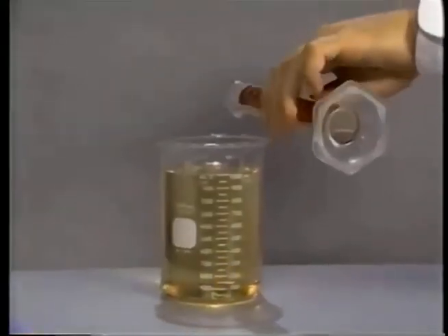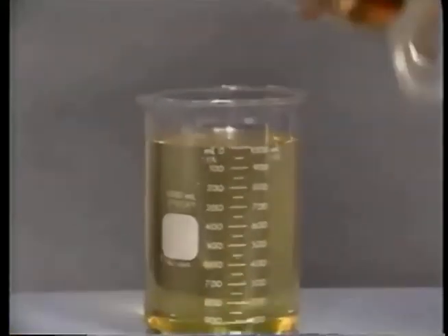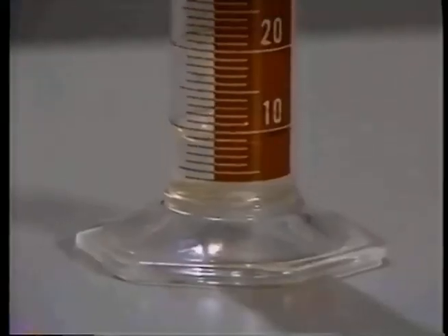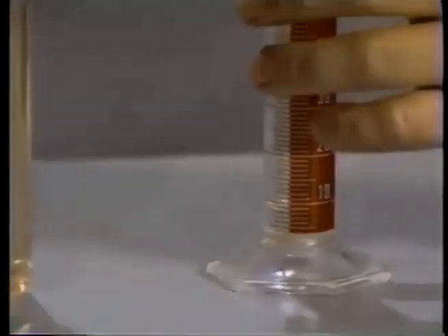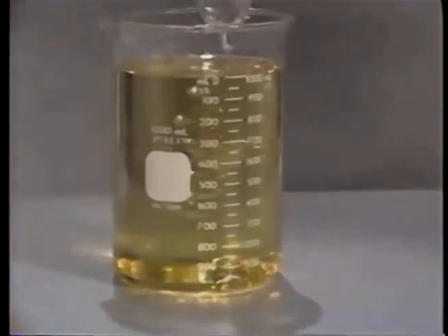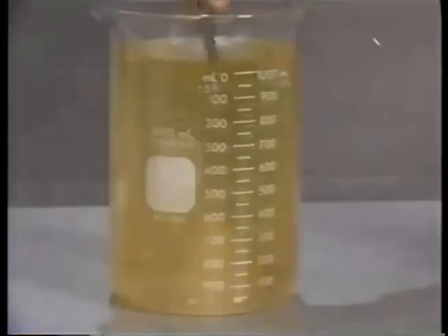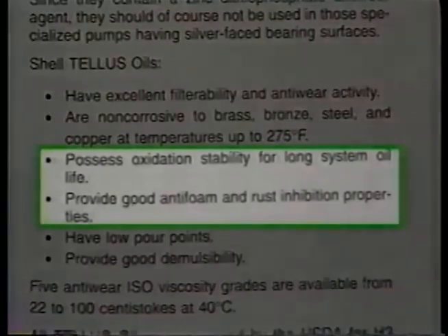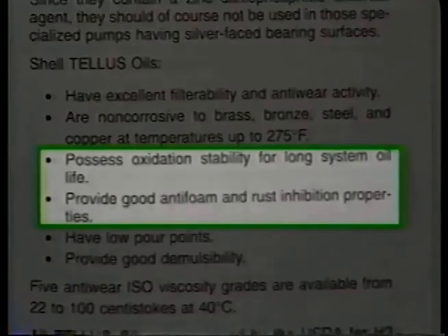Even small amounts of water in petroleum-based hydraulic fluids, less than half of 1%, can start to rust the system. However, except in critical systems, this isn't usually reason enough to discard the oil. If the water content is 1% or more, the oil will look milky. Oil manufacturers often add a rust and oxidation inhibitor to the oil. The rust inhibitor coats the metal surfaces of the system with a chemical film and retards rusting.